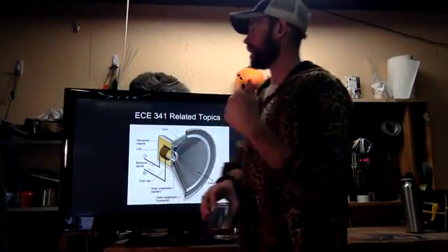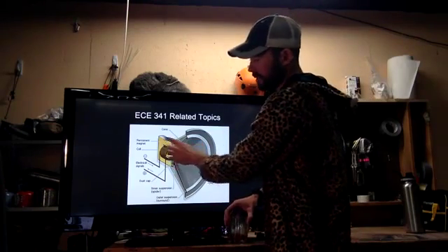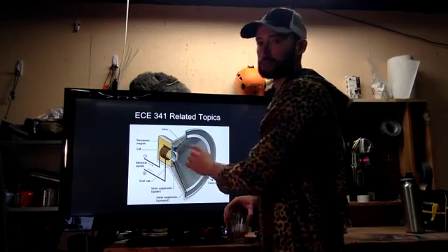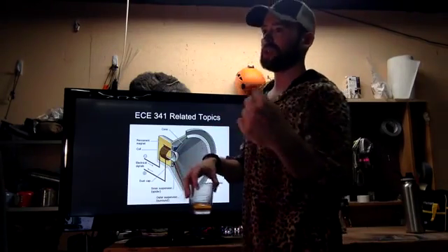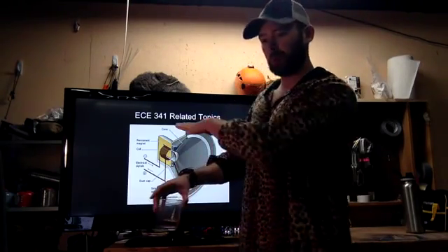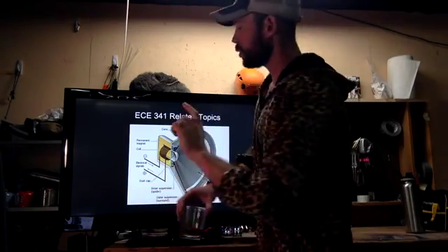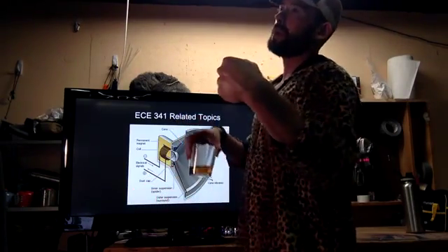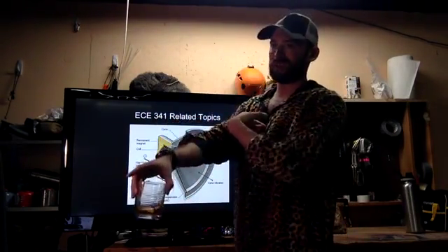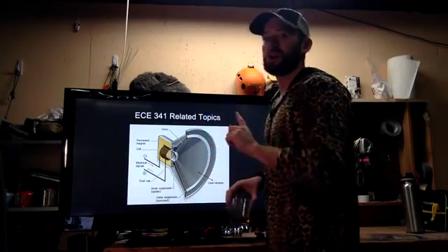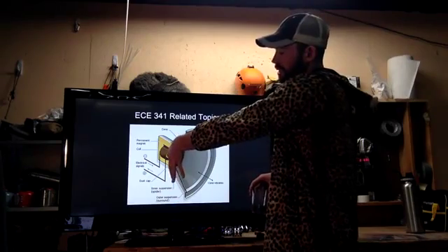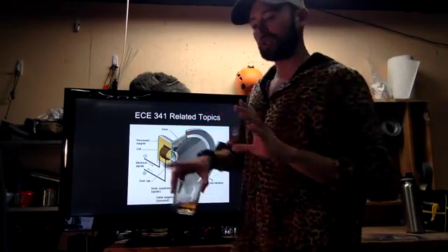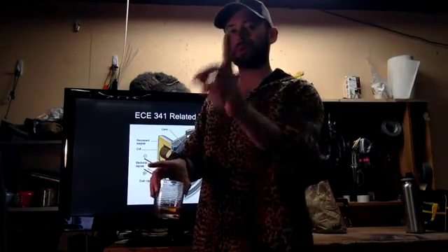However, when we put it inside of this permanent magnet, when the B fields are in the same direction, it's pushing in one direction, but when you change the direction of the current, the B field is actually attractive, so it goes the other direction. So that's how you create the oscillations in the speaker, which are kept in place by the spider so that it doesn't move laterally, it only moves vertically.